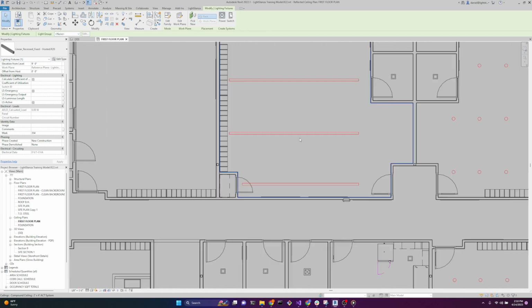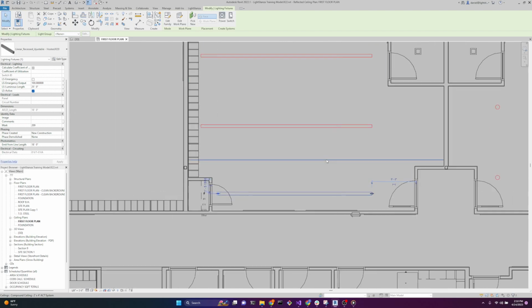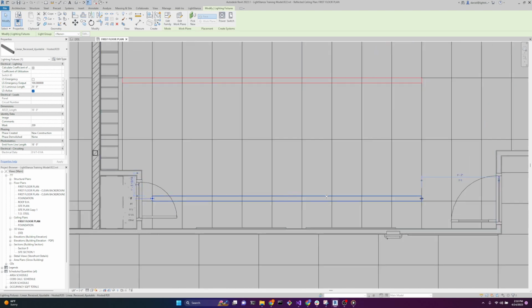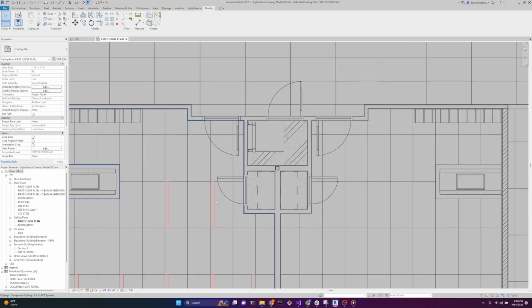And the emit from line length parameter is normally a type. So normally I wouldn't be able to assign it and control it from here. And so if I didn't change this emit from line length from a type to an instance, then I wouldn't be able to control the IES file centered position as I change the length of the instance-based linears, right? So with the type ones, we don't have to worry because everything is the same.